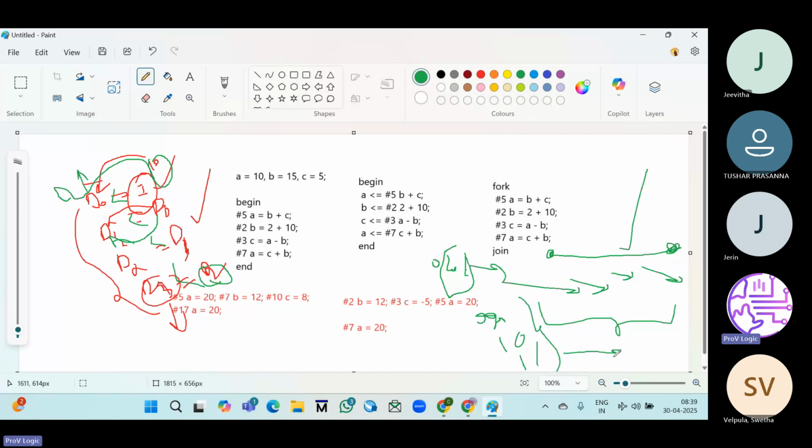Full case, in the sense, whenever we write all the conditions in a case statement, then we call it as a full case. Whenever we put the question marks, we call it as a parallel case. That means by using the question mark, we are generating the data parallelly. So in 4 cases, like 0, 0, 0, 0, 0, 1, 0, 1, 0, 0, 1, 1, whatever value we have assigned here will be assigned in all these cases. So that is what a parallel case and a full case.